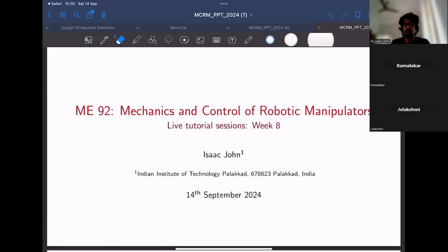Then we have also seen how we can apply the principles of kinematics and dynamics to a mobile robot. Just the same principles: how you can assign the frames as per the DH convention, then how to propagate the velocities and accelerations in the forward direction, then how to propagate the forces and the moments in the opposite direction, from end effector to the base.